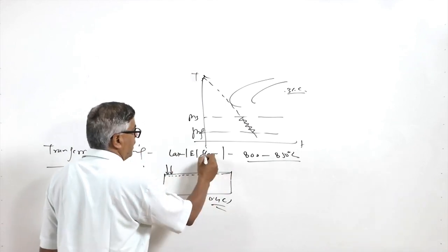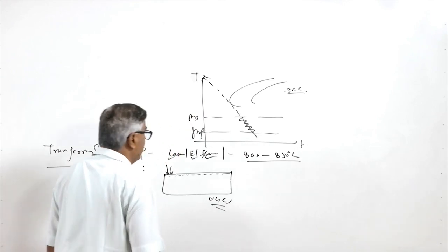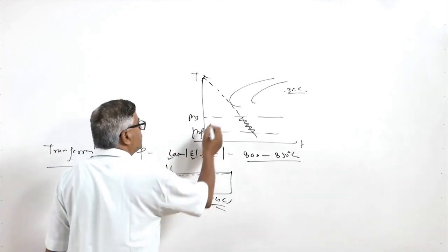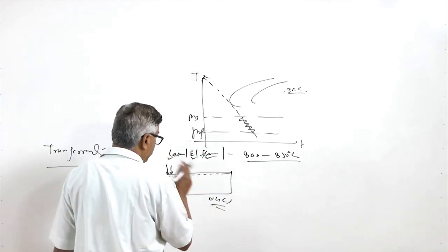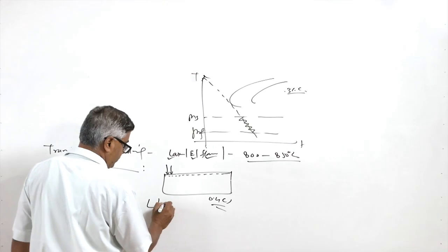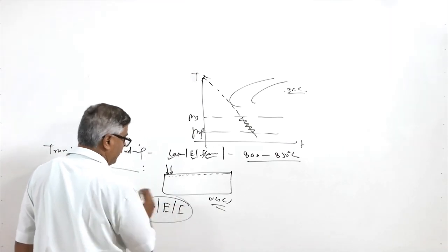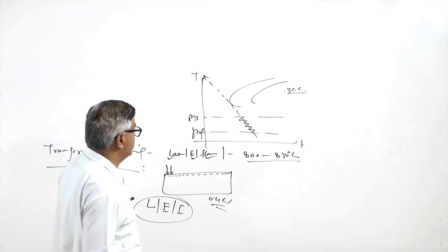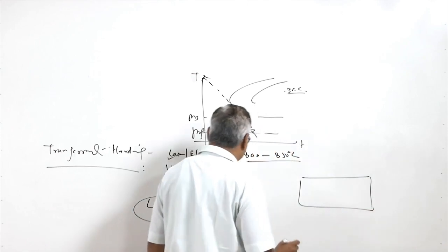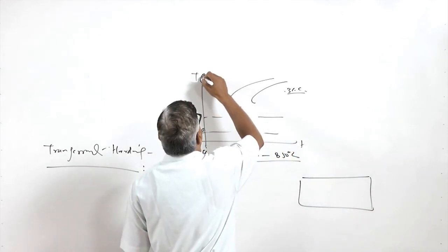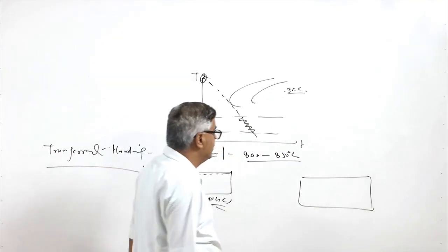For this, a flame, electron beam, plasma or laser, anything can be used. Once this homogeneous austenite is formed, in case of the laser, the electron beam, and mostly in case of induction hardening, no additional source of cooling is used, because the cooling conditions are so fast that austenite automatically transforms into martensite because of the high cooling rate experienced in these cases.